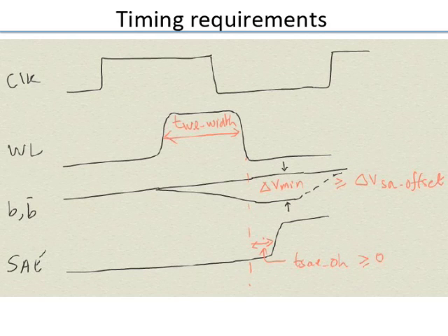Why do you need replica? Because in the case of the replica, you have to always discharge the replica bit. In the original memory circuit, there is bit or bit bar. Either of them can go. Second thing is the replica, sensing the replica bit line, I cannot use a standard clocked sensor, because if I use the same clocked sensor, I need to generate timing for that. So how do I do that? You use a different sensor, which is a simple inverter, which means the structure is a little different.